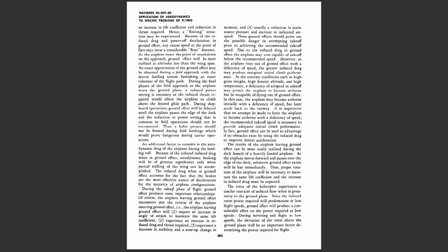An additional factor to consider is the aerodynamic drag of the airplane during the landing roll. Because of the reduced induced drag when in ground effect, aerodynamic braking will be of greatest significance only when partial stalling of the wing can be accomplished. The reduced drag when in ground effect accounts for the fact that the brakes are the most effective source of deceleration for the majority of airplane configurations.